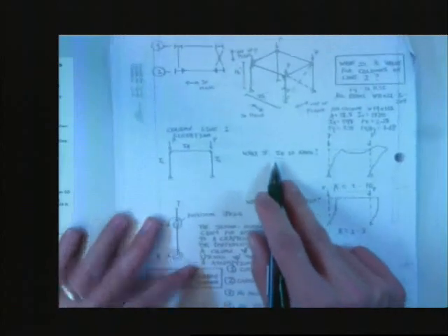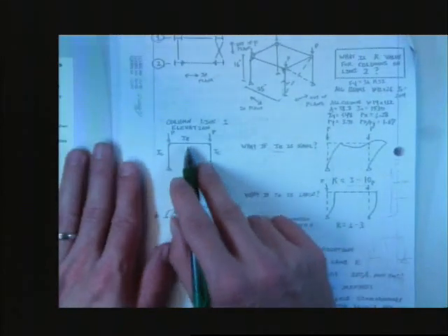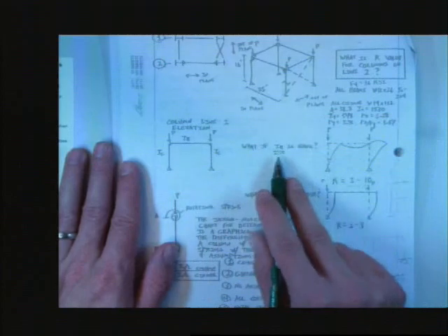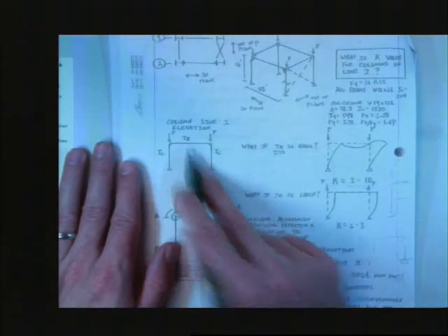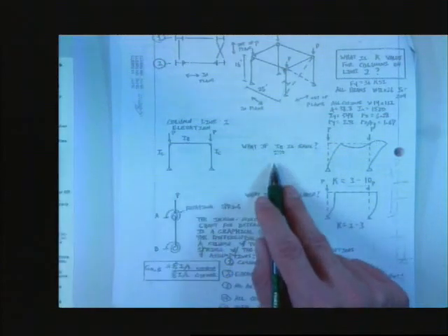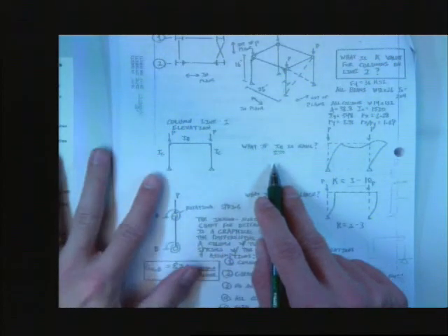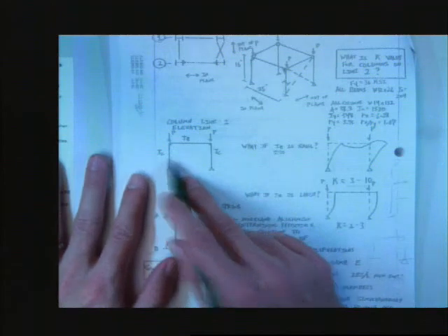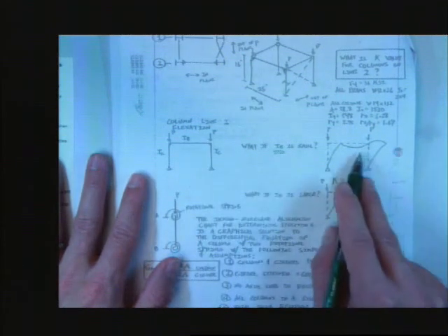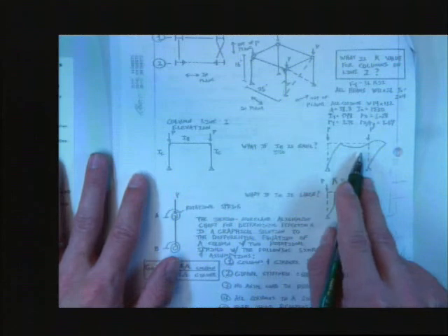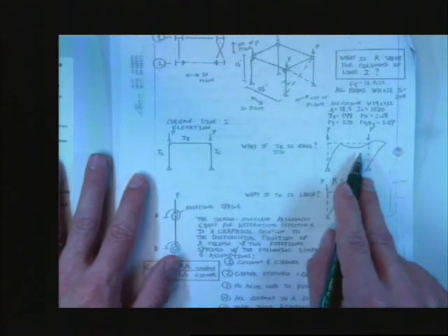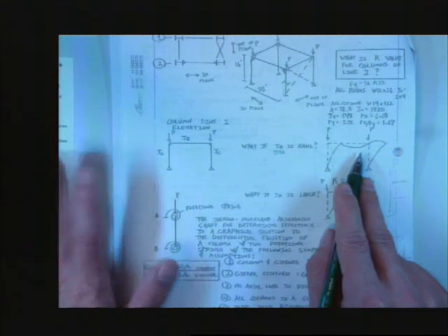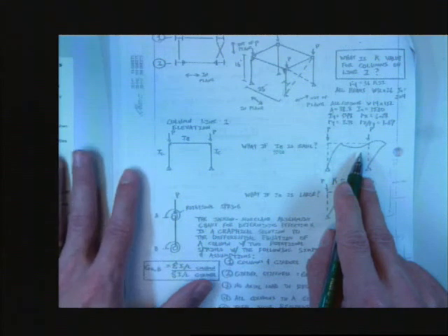What the alignment chart does is take into account if I_B, the moment of inertia of the beam, is small, like a noodle, like nothing with respect to the column. Then our deflected shape is going to look something like this, and our K is going to be high, something like 20. K at 20 is crazy high. I mean, redesign high. K at 15, I've seen it work before, but oh my goodness.